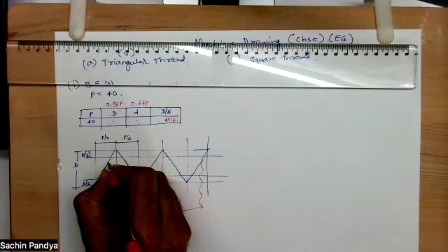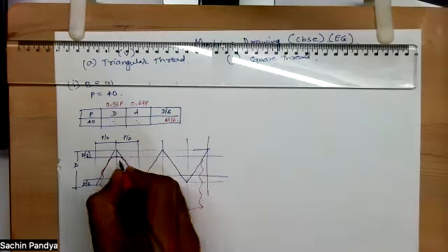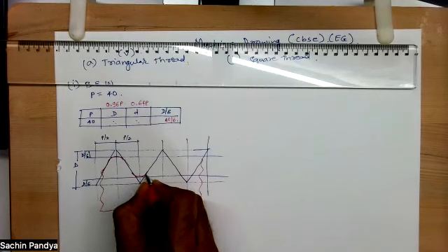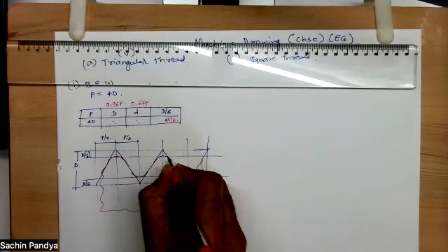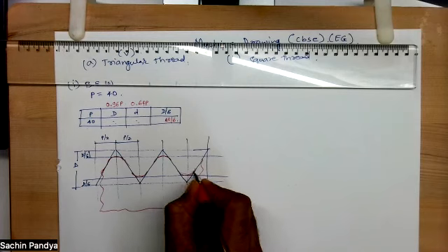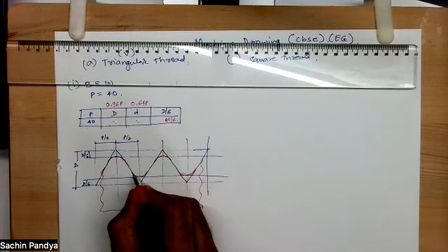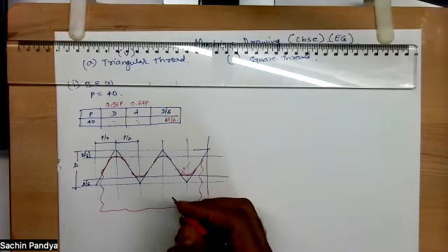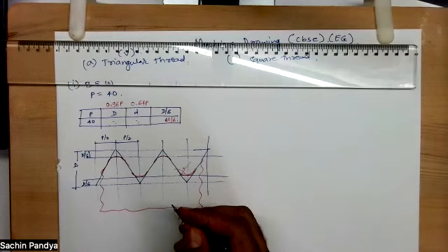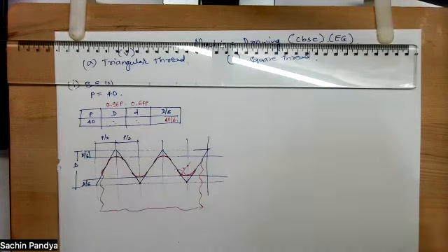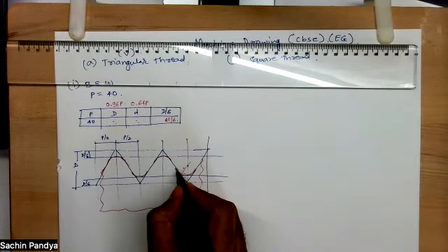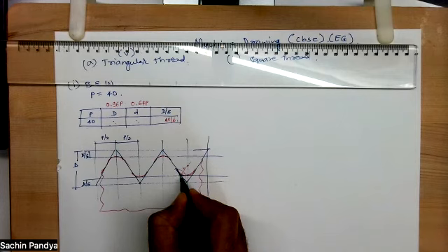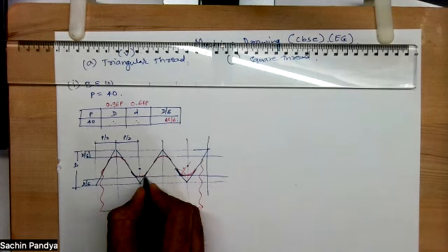Now over here, if you see, there is a curved part, a circular part. So how will you draw this curve? See this. To draw this curve, we need to bisect this angle, right? Wherever it cuts, from that point we can draw an arc. Are you understanding what I'm bisecting? I'm bisecting this angle. And then this point you can transfer here, so you can draw this arc.